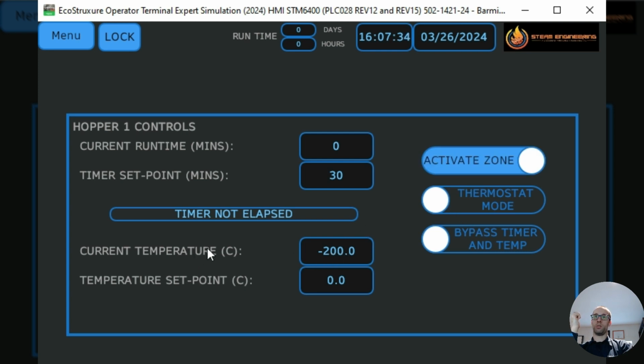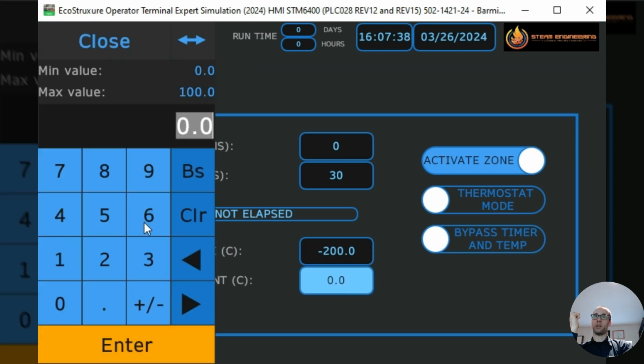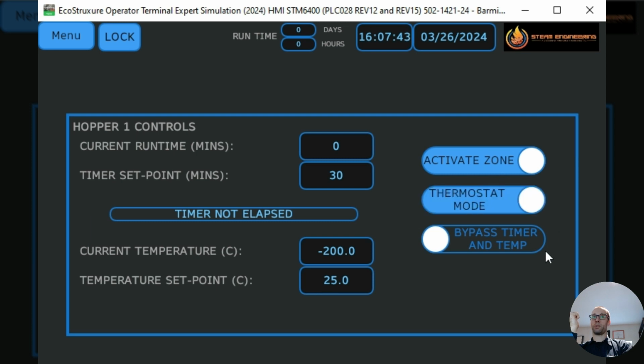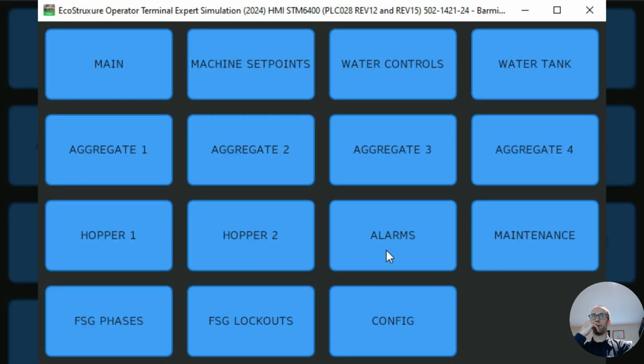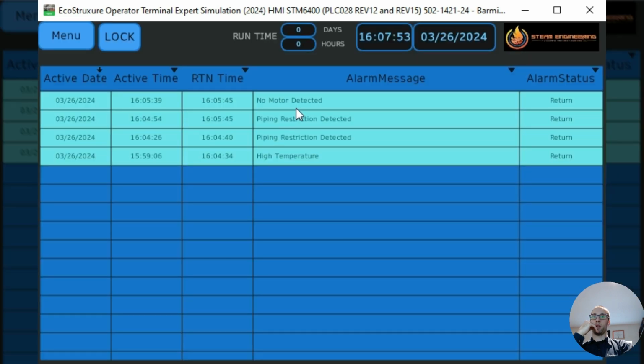Otherwise, if you want to monitor the temperature on the bin, we would hook up a probe to this and then set a threshold temperature of whatever you may want and then turn on thermostatic mode, and it will heat up to the threshold again and then allow a 3 degrees Celsius drop. All the alarm functionality and feedbacks are recorded for date and time.